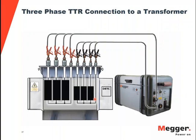Thank you, Diego. Next question is for Dinesh. When testing auto transformers, what considerations should we have? I will try to answer this in two parts. One is from the TTR point of view. As we were talking about the voltage dependency, you would run into some voltage dependency because you have three windings, and for the winding farthest away from the core, which is the high voltage winding, the magnetic coupling might be different. So if you're doing a turns ratio test, you might run into some voltage dependency. So keep an eye on that.